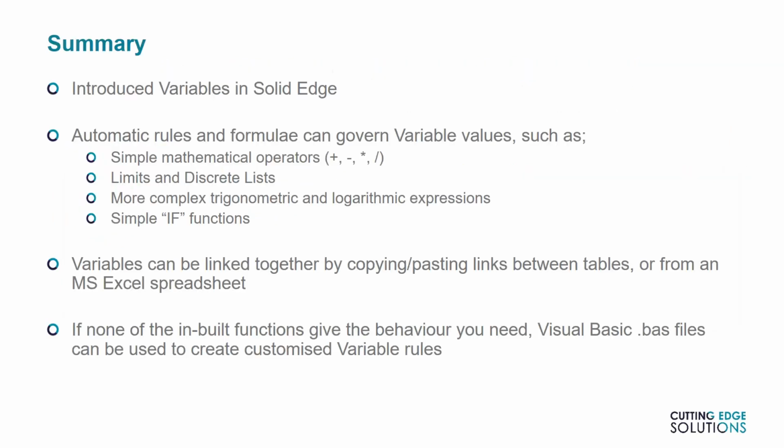In summary then, I've introduced the concept of variables in Solid Edge and how they can be controlled by user-defined rules of many sorts. I also introduced the concept of variable linking, even between different variable tables, or from an Excel spreadsheet. And finally, we looked at using Visual Basic scripts to govern variables with even more complicated logic.